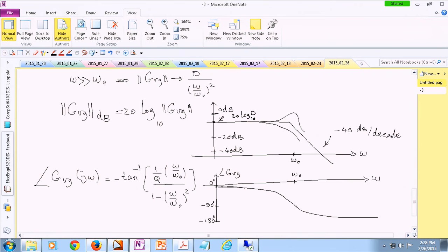So in the end, you see at lower frequencies, let's say if your frequency is somewhere here, you get an attenuation that is close to the value of the duty cycle, and you get a little bit of a phase lag over here. Once you increase the frequency of your fluctuations, for instance, once you go to this point, a very high frequency fluctuation, you have a huge amount of attenuation, from here to here.